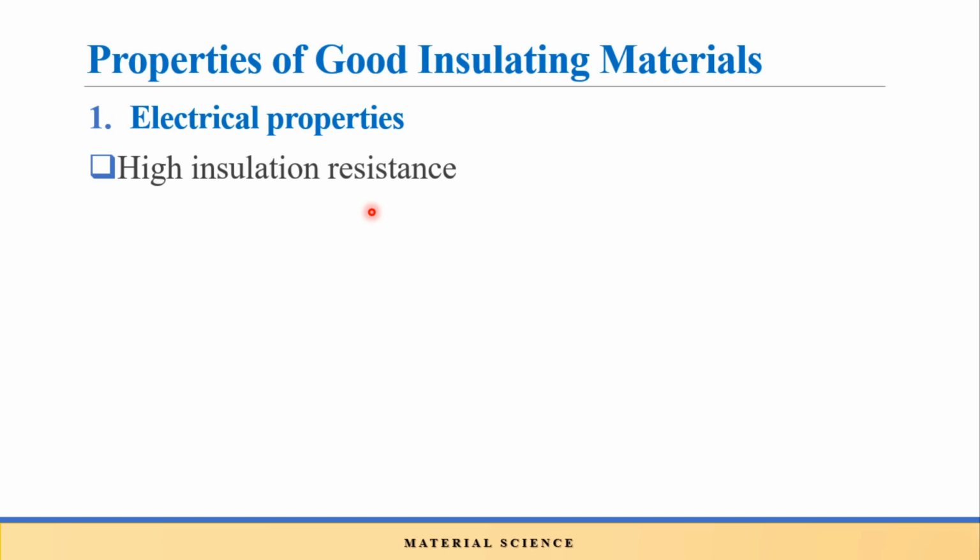Means temperature is affecting the insulation resistance. Again, due to moisture, there is a reduction in insulation resistance. If there is a presence of moisture content, then such moisture helps in transferring the charge, and hence the insulation resistance will get reduced. Again, we know that in case of cable, insulation resistance is inversely proportional to length.